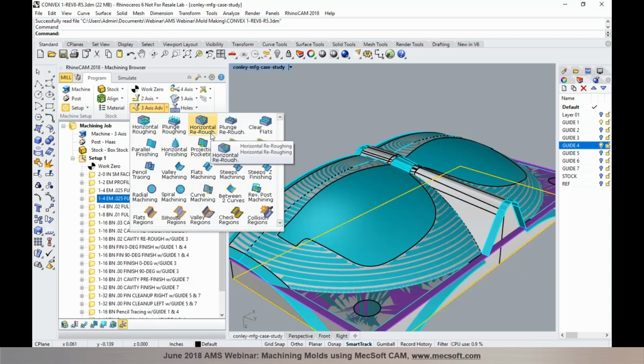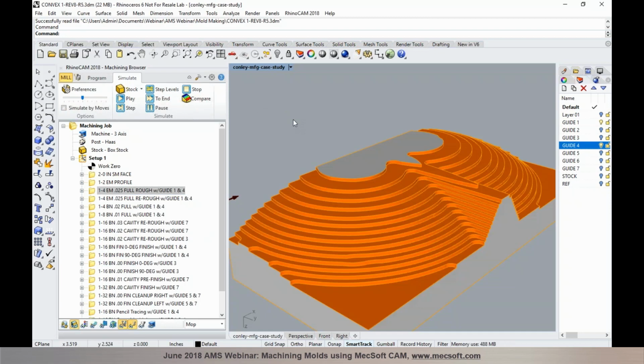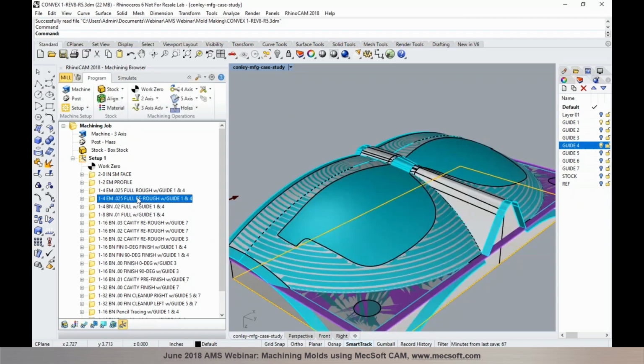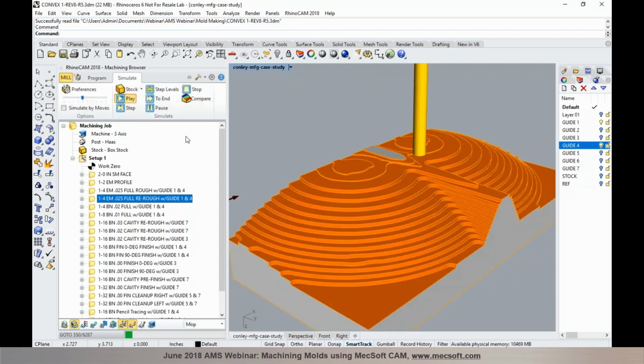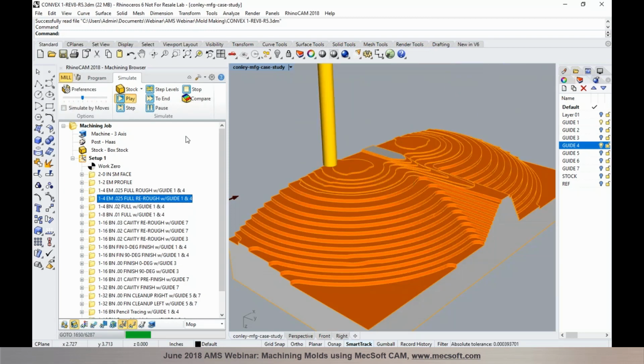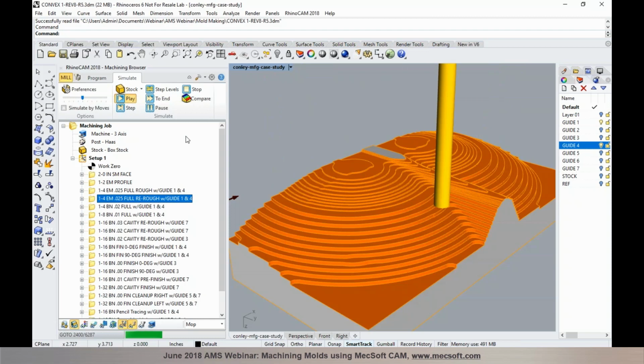The re-roughing operation takes into account the in-process stock that is being left from the previous step, meaning it takes into account what was already pre-cut from the previous roughing or pre-finishing operations, and it creates another secondary roughing operation to go back and remove some of the uncut material from the previous step. So in this particular step, you're not going to be cutting air, you're actually saving a significant amount of time in basically going back and roughing it again, either with a tighter step over, a tighter step down, a smaller tool, or leaving less stock from the previous process.